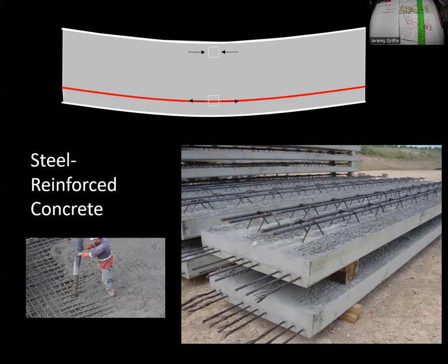Now I can tell you what Romans did not do with concrete, though. They did not create second floors. You guys know we're sitting on a second floor right now. There's a void beneath us. Romans could not build the structure that we're on right now. Why is that? Well, because even though concrete has a huge compressive strength, it has a tiny tensile strength. So just think of those toothpick bridges that you guys created. The bottom part goes into tension, and then cracks will form, and the concrete will just crumble really easily.